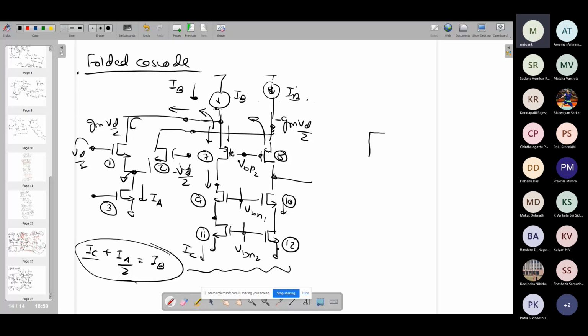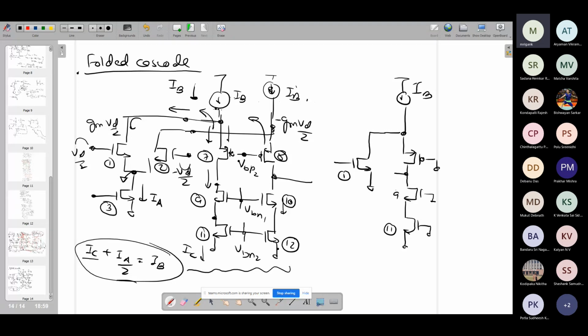The half circuit is simple, right? So you just have the input pair M1, it is AC ground, and on the other side you have IB, and you have the cascode. This PMOS gate is AC ground, and then you have two NMOSs. Gates are AC ground. Output is here. Is this okay? This is your whatever 11, 9, 7, etc. So is there any problem in this?